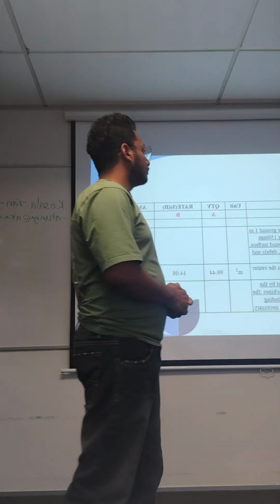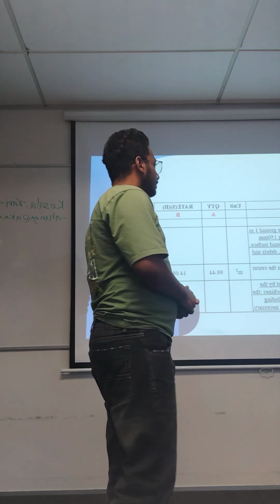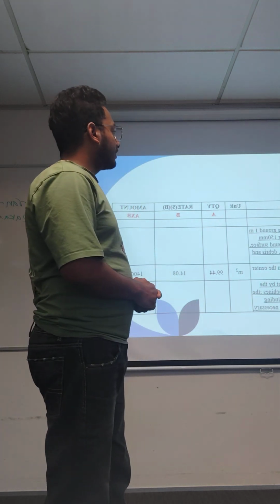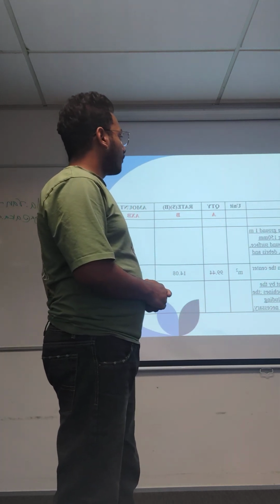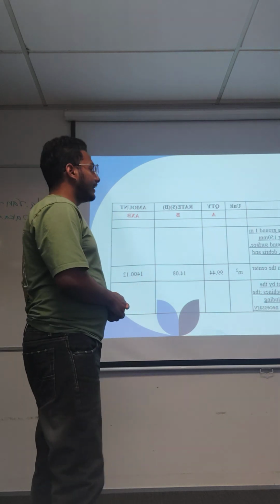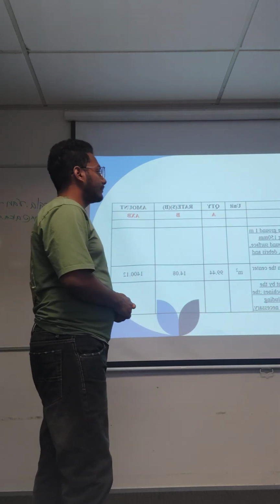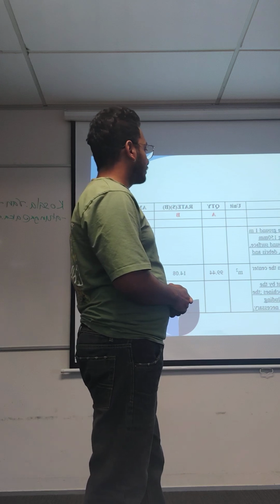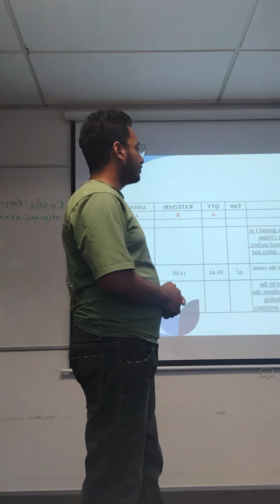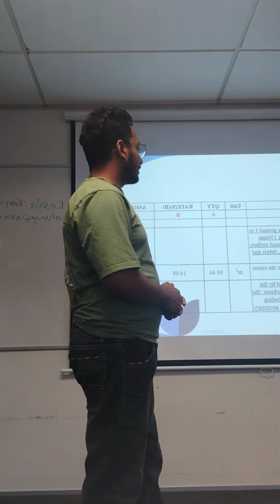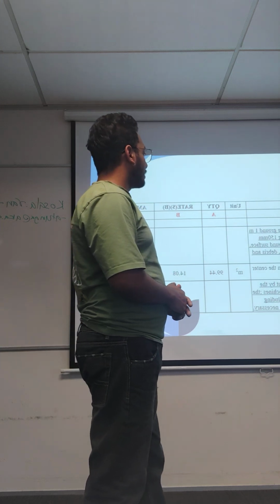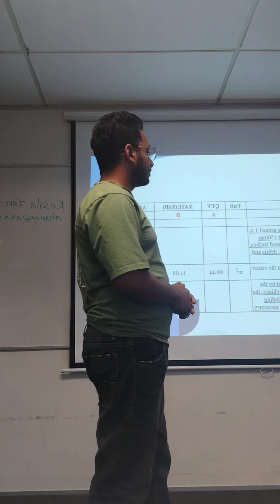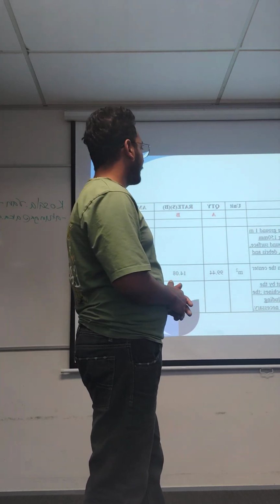Prepare SOQ. Description: earthwork. Contractor has to clear the ground from 1 meter away from the grid by removing 150 mm top layer from the existing ground surface, including but not limited to removing trees, roots, drives and other disturbances as necessary.